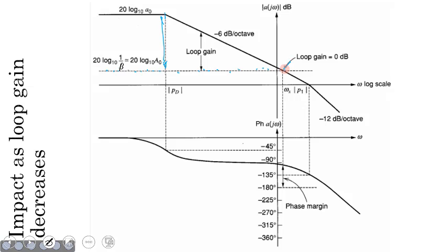So here is where our omega equals the gain crossover frequency, right? Which means that our closed loop will have a bandwidth of this much. It starts all the way from this particular frequency to a frequency that intersects with our omega gx. So that is the bandwidth of our closed loop system. In a way, we have reduced the open loop bandwidth as well as our closed loop bandwidth. So that is the drawback of this particular system.